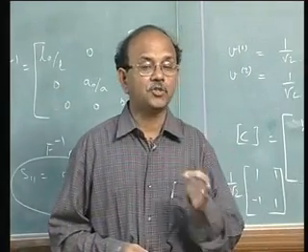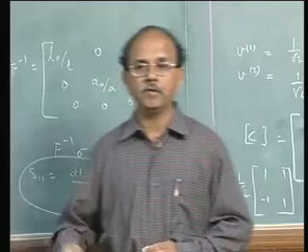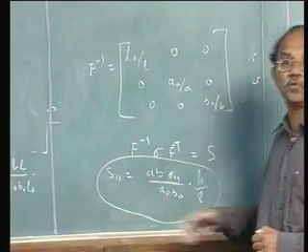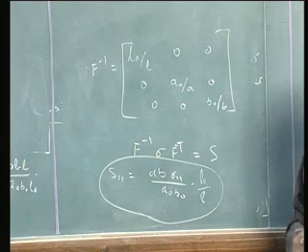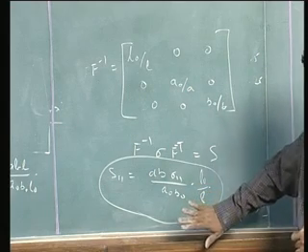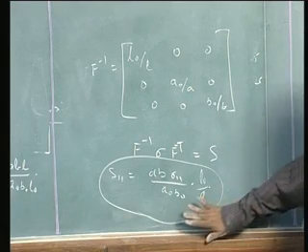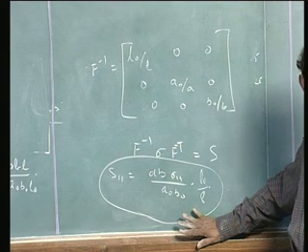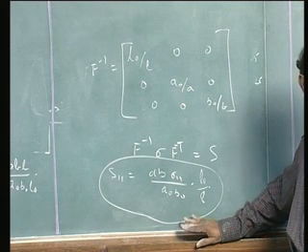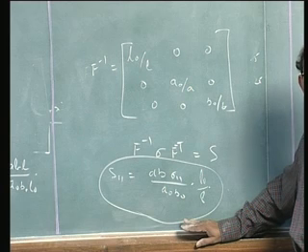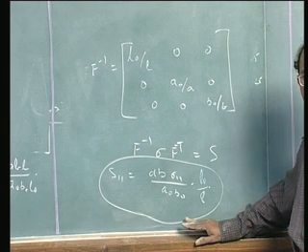But that should not worry you when we apply these things, because you should view it as a mathematical operation of pullback. So, that is the reason why apart from theory, you will not see these things in results. The results are still given in terms of the Cauchy stress. All the results that are still given in most of the softwares are in terms of the Cauchy stress.